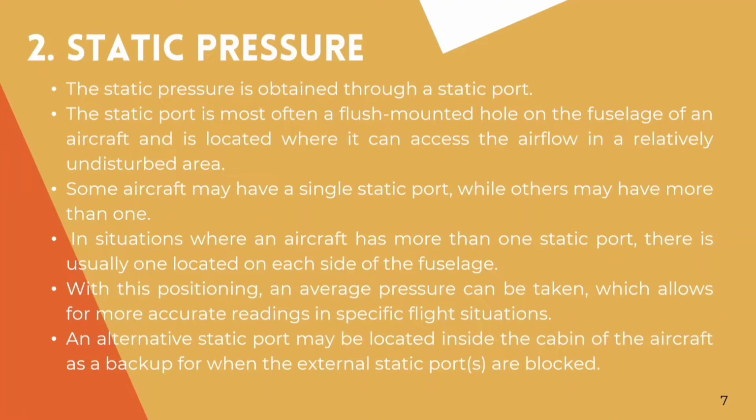the fuselage. With this positioning, an average pressure can be taken, which allows for more accurate readings in specific flight situations. An alternative static port may be located inside the cabin of the aircraft as a backup for when the external static ports are blocked.